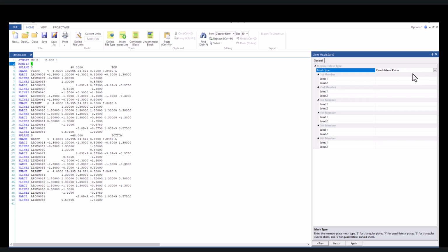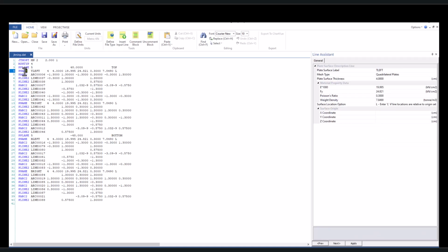We're gonna leave it as plates for this sample, but you can use shell elements by changing it. You also may change here in every P name line. Hey, this is release 2023. Maybe for the next release, they will make a change and there will be an option in the Joint Mesher GUI. But so far, we have to do this manually in DataGen.